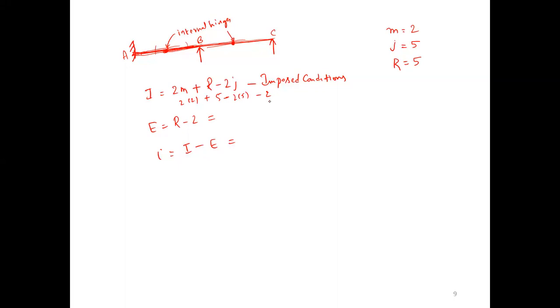Minus 1, sir. If you are getting minus, then you directly say that the structure is unstable. Optionally minus 2, negative, the structure is unstable. Sir, minus 3. Whatever it may be, if you are getting a minus value, the structure is unstable. The structure is unstable. Got it?